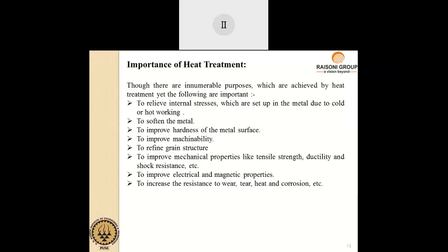Above 900 degrees Celsius, with 0.8 percent carbon, which phase exists? It is austenite, denoted by gamma. It has a crystal structure of FCC, face-centered cubic.